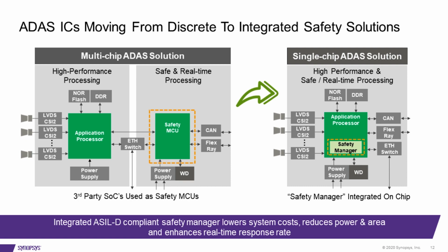So there's two ways to do it. You can allocate some of the processing resource of, say, the application processor. Say you have a multi-core application processor for an ADAS chip, as an example. You could allocate some of the processing capability of one of those processors to safety-related management tasks, but that will have an impact on the overall performance of the device, plus it could potentially compromise the isolation between the safety-related and the functional aspects of the device.